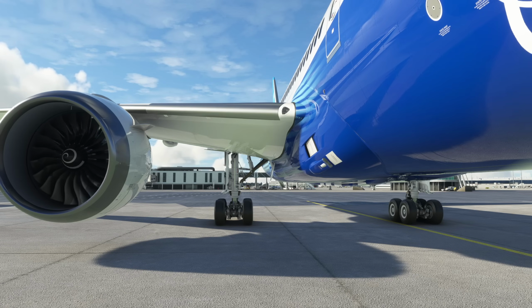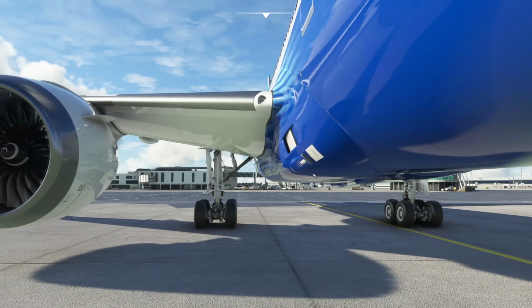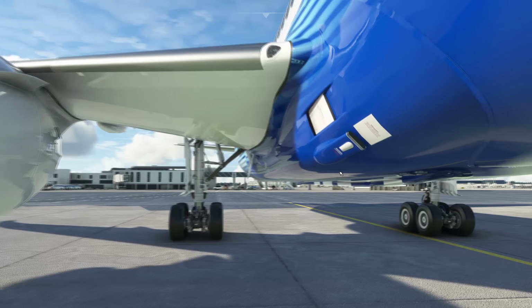It was common on the Airbus to actually turn off the air conditioning packs. That way you stop taking away some of that bleed air during the takeoff process. Saves a bit more fuel. So the 787 got around that. We'll have the engines operate super efficiently, thank you very much, by not tapping off the air for pressurization, and we'll do it with a different system, and that's what we've got here.